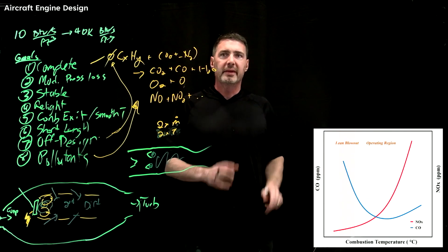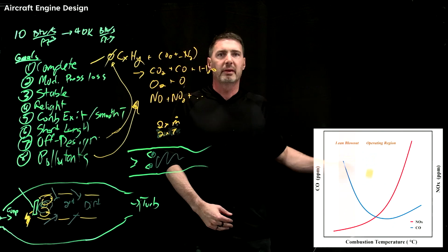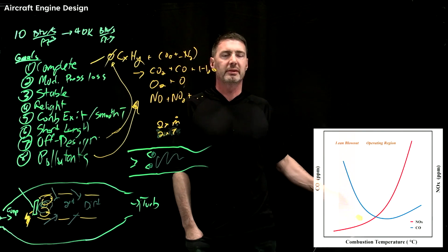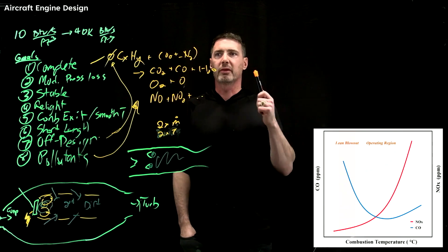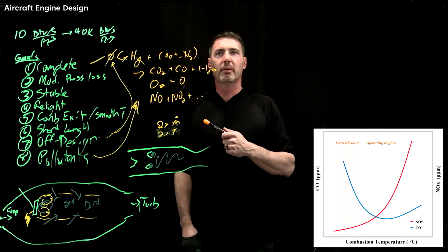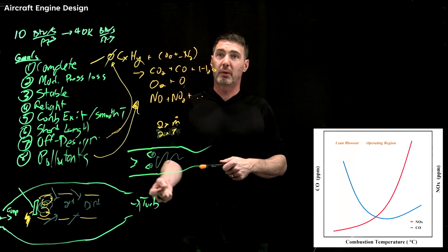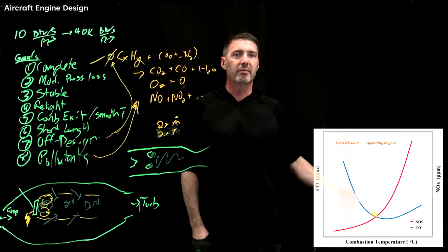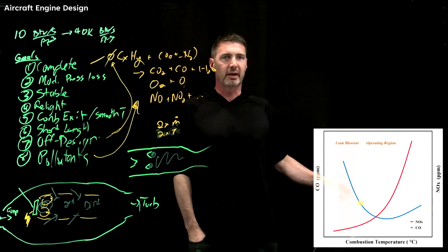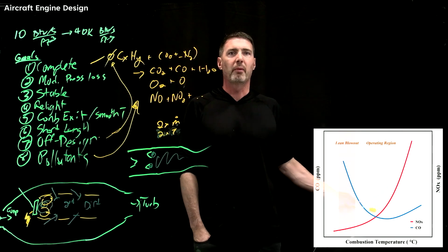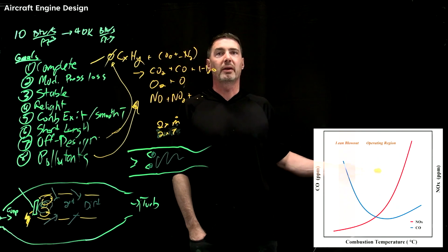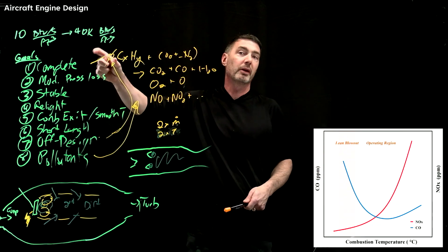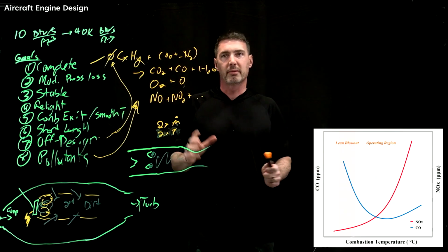Okay, and then this diagram is a good one talking about the challenges of that operation and combustion temperature. I was talking about burning fuel-rich for stability in combustion, then quenching lean. You can see here the combustion temperature in terms of where you're minimizing your NOx and your CO2. That gives you an idea of where you might want to operate. But based on your throttle and things like that, you have all these conditions. This lean blowout would be where you're throttled down too much, or the right kind of conditions.